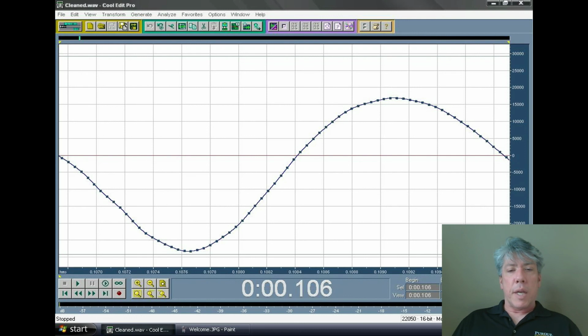So it's important to understand that these analog signals are going to be discretized in amplitude and in time, because they'll just be sampled every time the PLC goes back and looks at the inputs, which doesn't happen at all times. Now if you've got a process that responds a lot faster than the PLC is capable of watching, you need some other system. You need some way of dealing with that. Now there are so-called high-speed inputs. They are typically for the digital world, not the analog world, where you have a counter or something that, if you've got really high frequency pulses, it can count them because the scan time of the PLC is too long and will miss a bunch of the pulses.